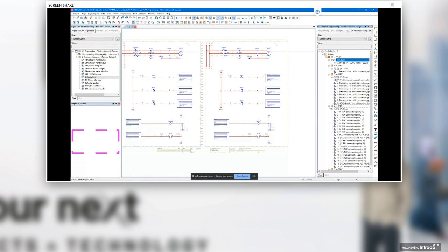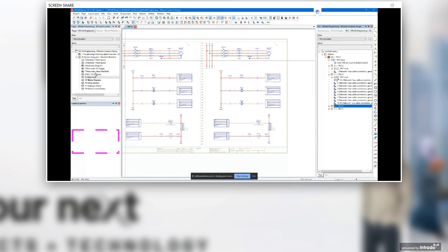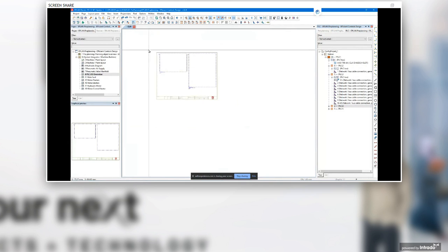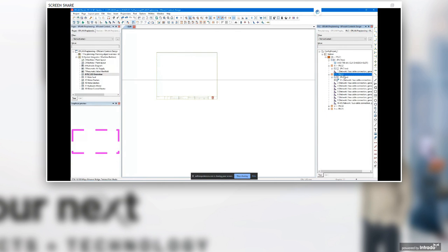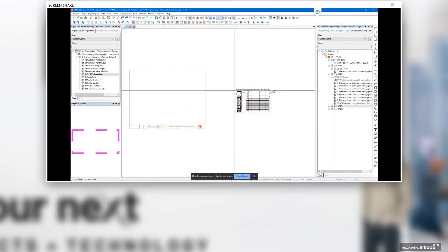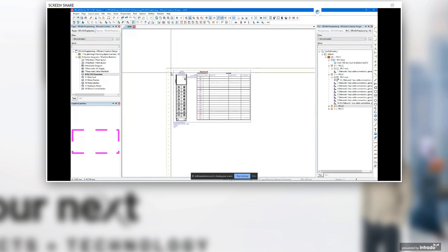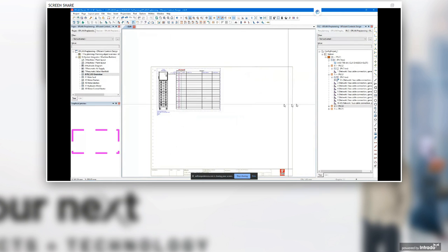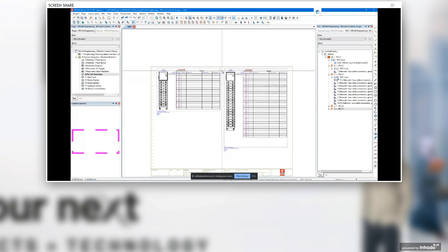So let's go over to an overview. On an overview page, I'm just going to clean this up, and now I can just take my PLC I/O, this one here, just drag it onto here, and this would showcase the I/O module, which has not been wired yet. So this is my IB16, and I can just drag my OB16 as well, and lay it out here. So this is an overview of that PLC card, showing me which I/O points have been used or which ones have not been used yet and are available for use.